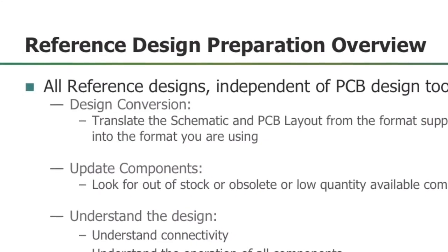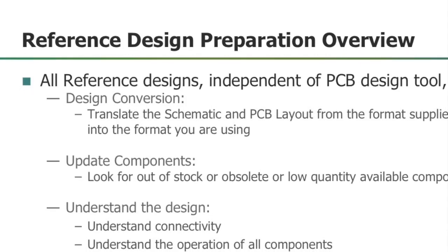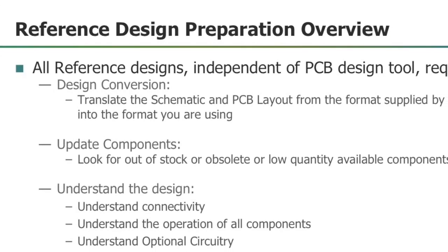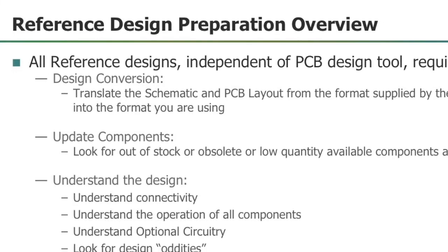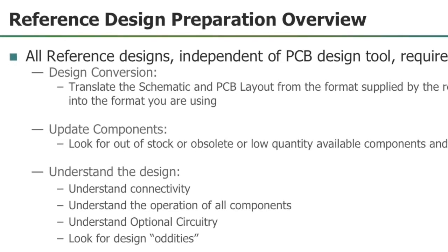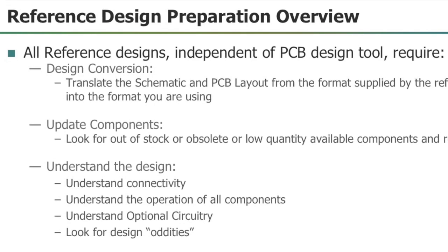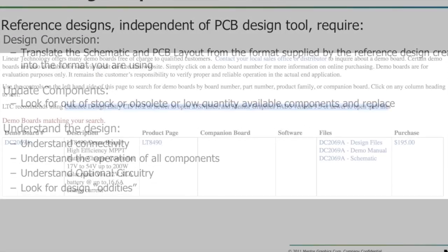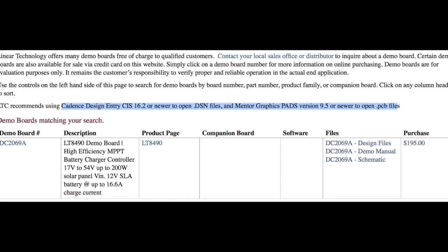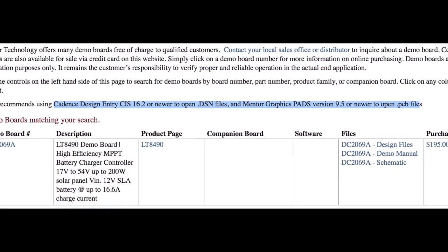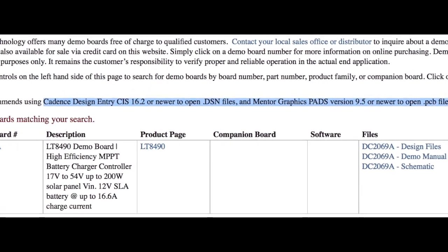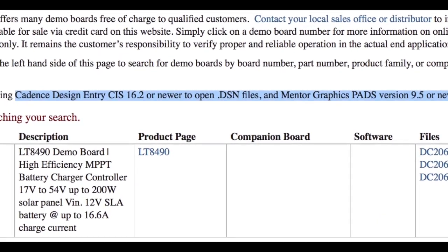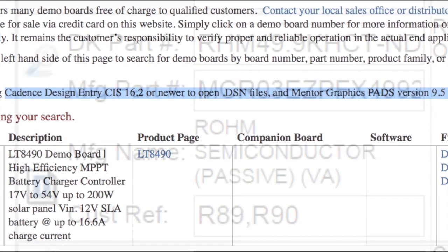Working with Tom revealed there are common steps every design engineer must progress through in order to leverage a reference design. The steps are conceptually PCB design tool independent and reference design independent. The fundamental challenges are converting the reference design source format. Component suppliers don't publish the reference designs in every EDA format. In fact, the Linear Technology reference design has a Cadence OrCAD schematic and a Mentor Graphics PADS physical layout.